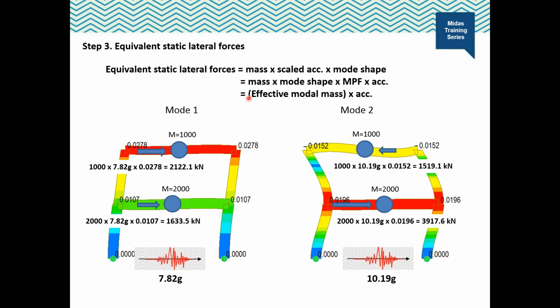As the third step, we need to compute the equivalent static lateral forces. The static lateral force for each floor will be determined by floor mass times scaled acceleration times floor mode shape.